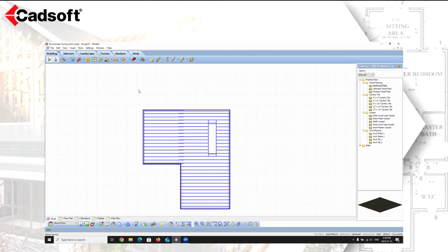The structural floor can then be modified to add in bearing lines and adjust the framing base points. The floor tool can also be used to add in framing by specifying the floor as a frame floor and then assigning the correct members to their floor components. The floor tool adds in your floor finishes like tile, carpet, or hardwood, and then can be elevated to the right height based on the material that is being used.